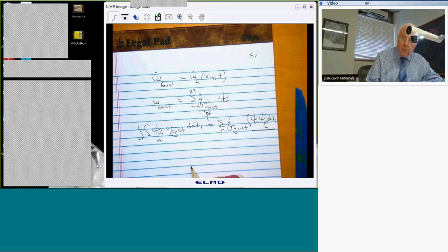So if someone tells me what the gust distribution is, I could represent it in terms of mode series, in terms of structural modes. But that's just a convenience. It's not that the gust is determined by the structural modes. It's just a convenient representation, because my interest in the gust for aeroelasticity is not in the gust itself. There are meteorologists who are worried about the gust for its inherent sake, right? But I'm only interested in how it excites or doesn't excite some of the structural modes. So this representation might actually be useful.